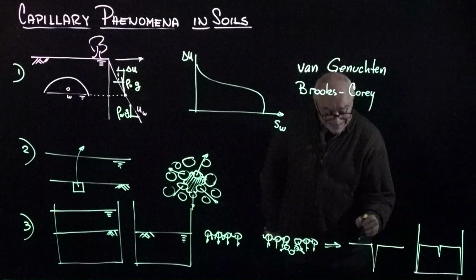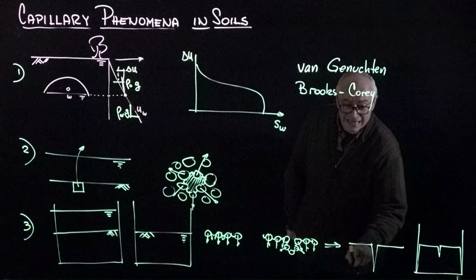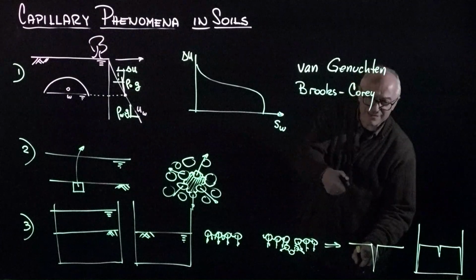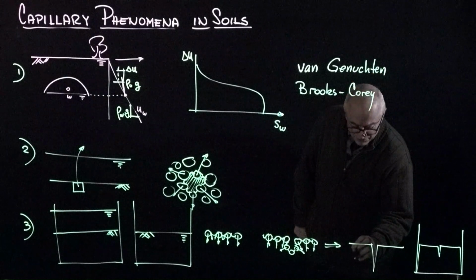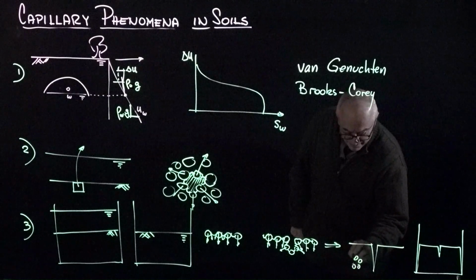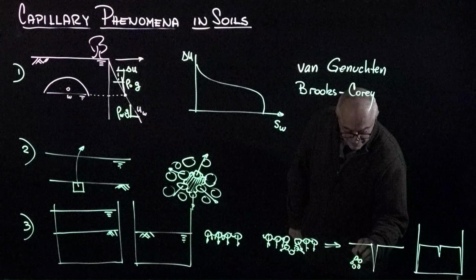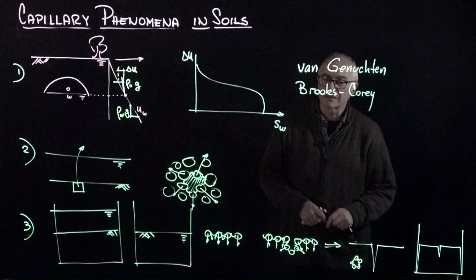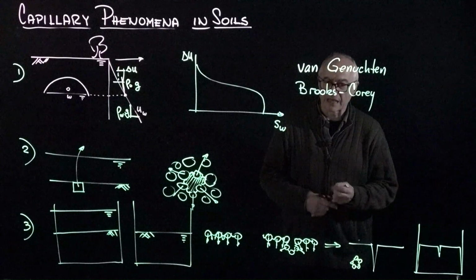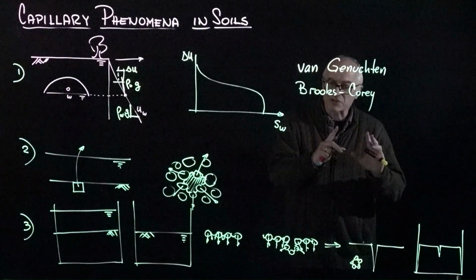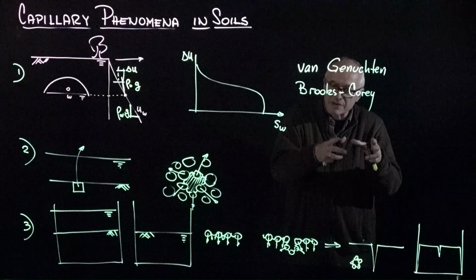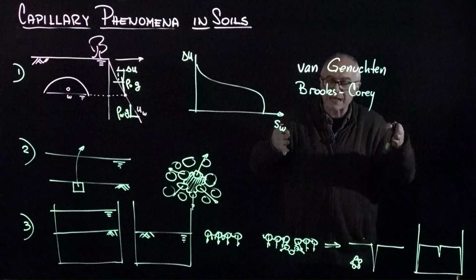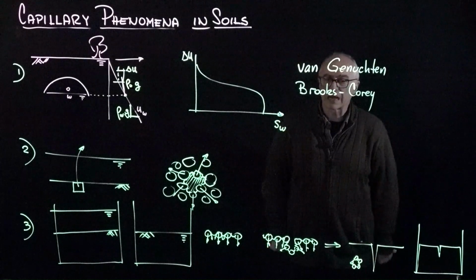Now, the suction that is developing in the soil inside here lowers the water pressure. The water pressure decreases, gas may come out of solution, and if gas comes out of solution, grains inside here may also be pulled apart by the expanding air bubble, and internal desiccation cracks periodically form in soils. We have been able to observe them using micro-CT, putting soils that are drying inside the micro-CT, and you see how bubbles nucleate and begin pulling the soil out, and while fractures are happening at the surface, internal fractures are also developing.